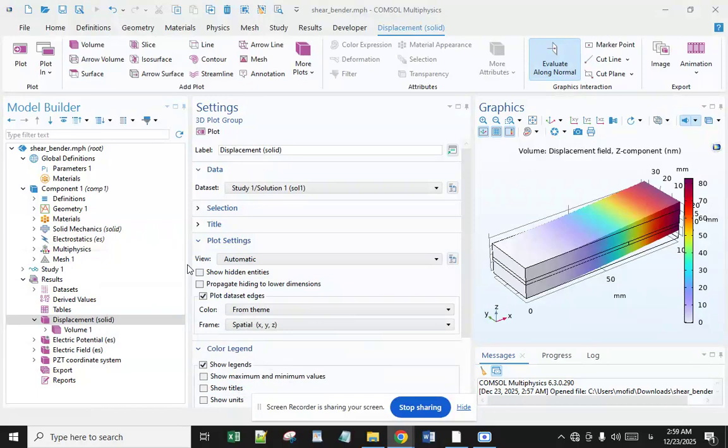The sandwich construction is made of unsymmetric thin faces, Euler-Bernoulli beams, and a relatively thick core, a Timoshenko beam. The obtained two-node finite element has only four mechanical degrees of freedom, which are the deflection and its derivative, and the mean and relative axial displacements of the faces' midplanes.